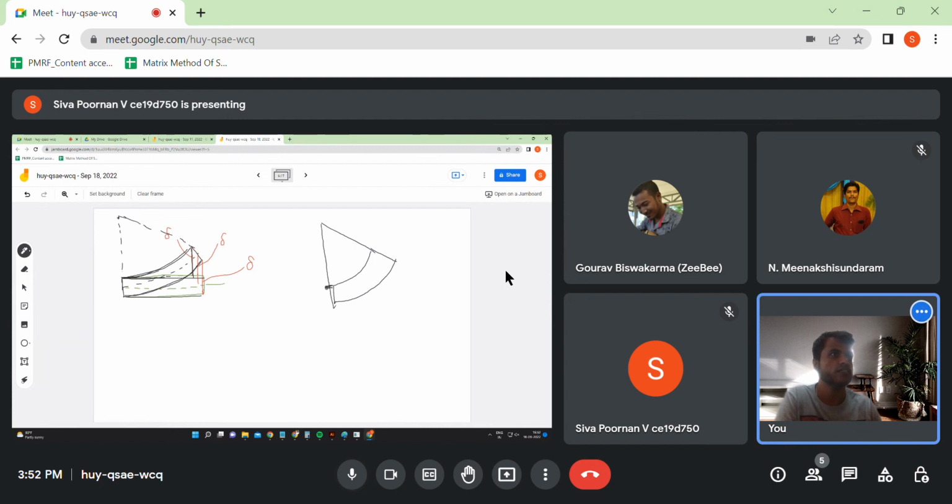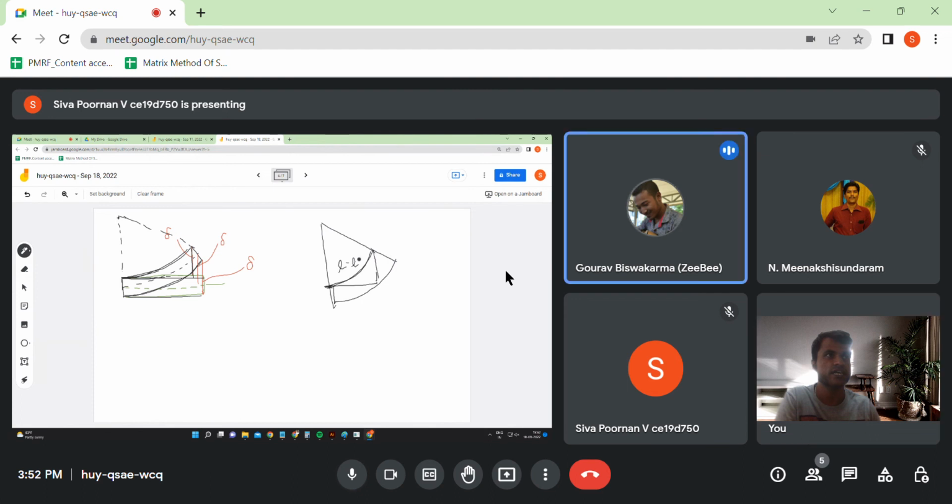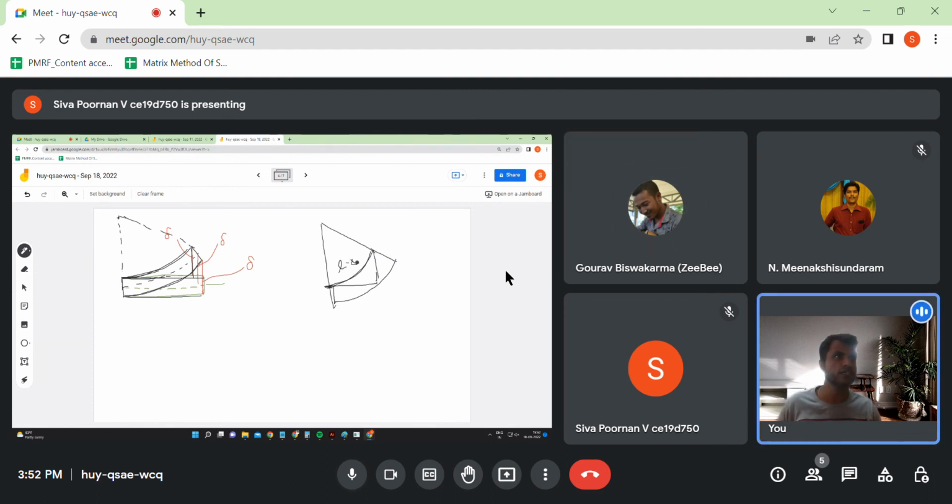You find out what the height difference is between this point and this point. If the initial length was L, then this one will be L minus delta L, and this arc will be L plus delta L, and both of them will subtend angle theta at the center. So you have L plus delta L, and see what this height is. You will actually see that the difference between the initial height and this height is of second order, not first order.